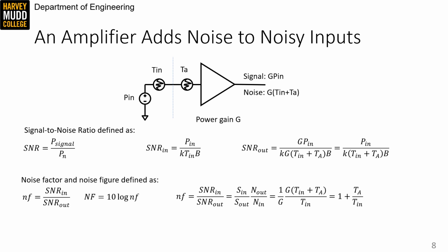However, it is telling that the amplifier's noise is added to 1. The 1 term in that equation comes from the fact that the input temperature gets amplified and sent to the output, which means that the noise factor always has to be greater than 1. Every practical amplifier adds some noise, so it will always make your signal-to-noise ratio worse.